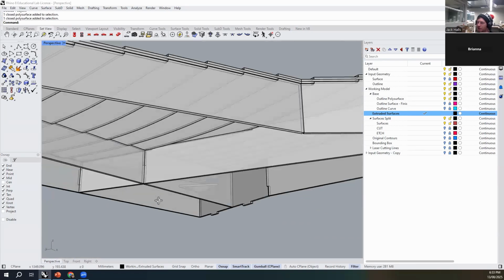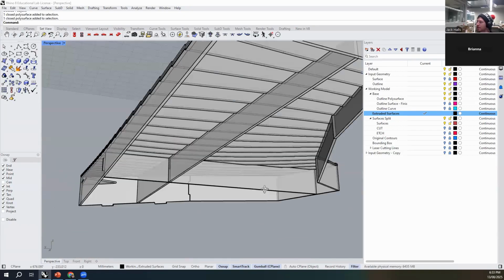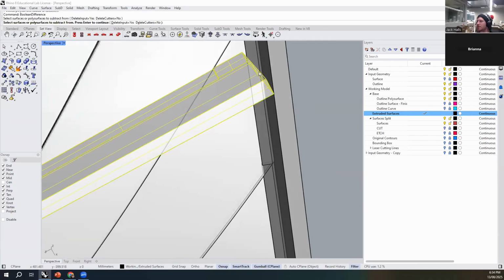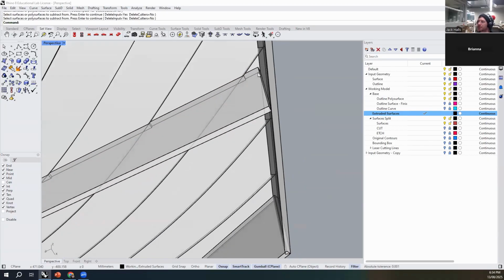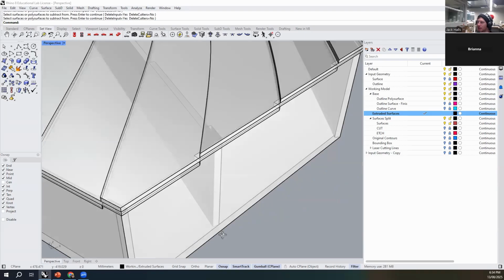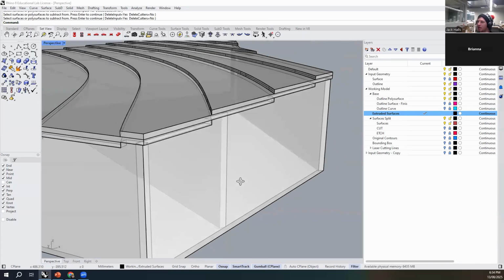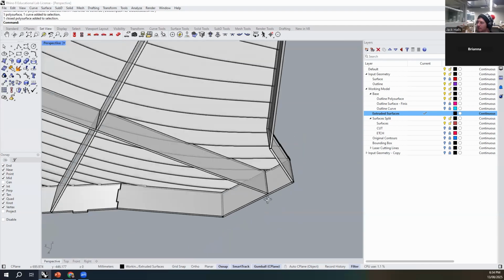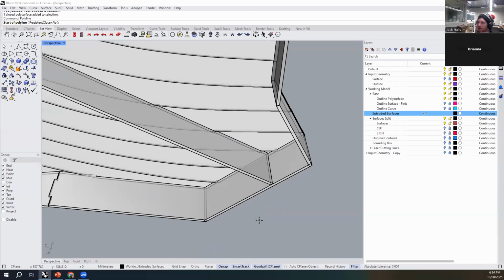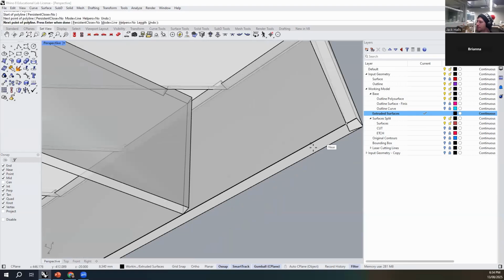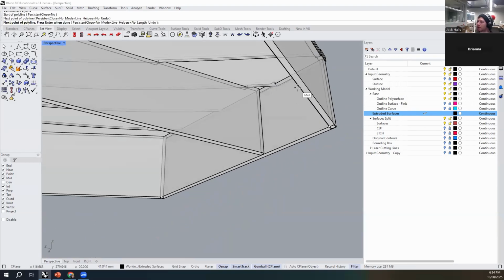Okay, great. The final thing that we'll look at, the second final thing that we'll look at, is what I was saying about, okay, well, what do we do about this? This joins to this. Now, you could just put another finger joint through that face. That would be fine. You'd have to do a little bit of remodeling, okay? But another way would be to sort of think about the logic of our wedge piece again here. So I could just go ahead and use the polyline command, assuming that I've already resolved these corners as you will. And draw that out there, draw that edge.